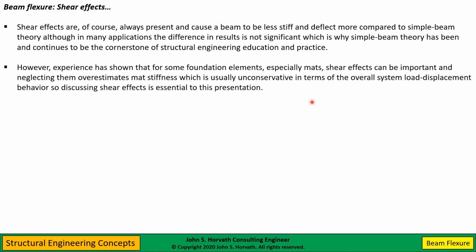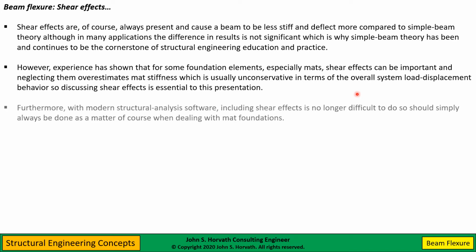However, the reason I'm emphasizing it here is that for some foundation elements, and certainly this is true of mat foundations in general, shear effects can be important. And we don't want to neglect them because that overestimates mat stiffness, which is in general, for a mat foundation, you don't want to overestimate the stiffness of the mat and the stiffness of the overall system flexibility.